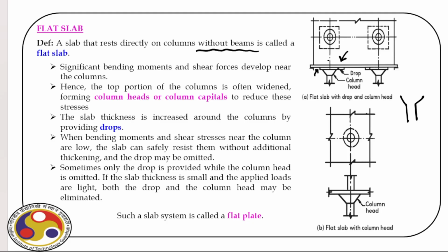So when we design, we have to actually design the size of these drops, and we have to design the reinforcement accordingly. Now, sometimes we may avoid this drop panel if the situation permits, but as the moment and shear force increase, it is always better to have a drop panel here. So we can have a drop panel, or sometimes we can avoid it depending upon the situation.